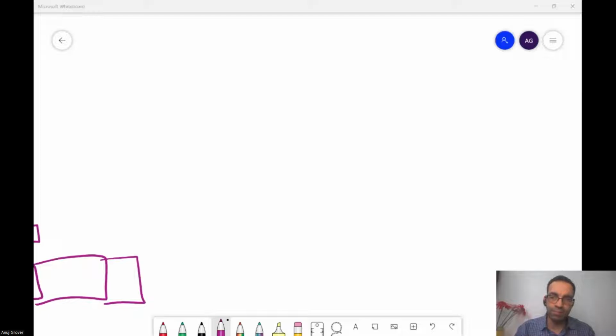Okay. So, like what we studied in class, write driver would be implemented in that IO circuit part, and negative bit line voltage would be generated in the write driver circuit part. Yes. So again, the constraint for the negative bit line write driver team would also be that they have to match the layout in such a way that it can be used in the IO that the IO team designs. So they can simply remove the write driver of their IO and plug this one in. That is the intent. There would be some increase in area, that's fine, but it should be doable.